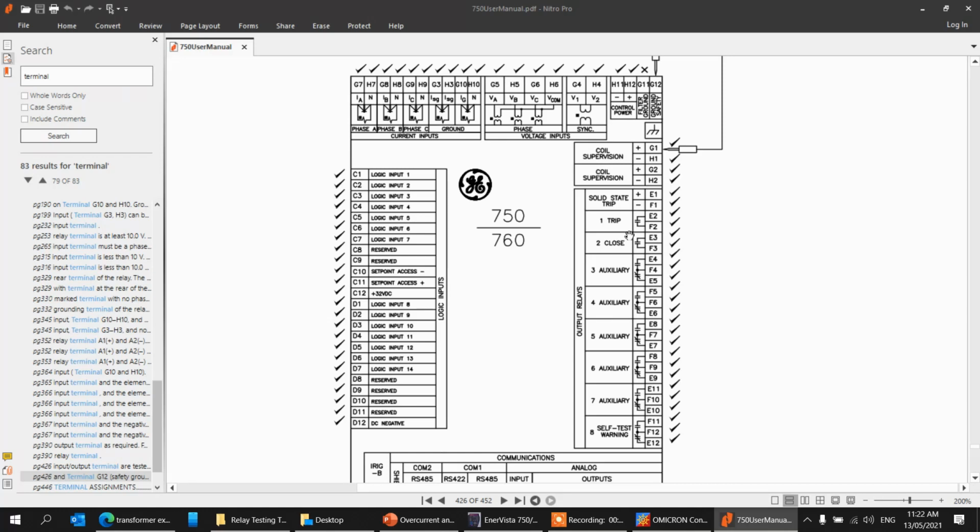In the real world, you have things to consider, like intertrip and connections and everything. So if you never consider that information, it looks like you're doing bench testing, but it will affect other systems as well. So that's the difference between bench testing and the actual one. That's why, as Francis always mentioned, the best material you have on site is the drawing.